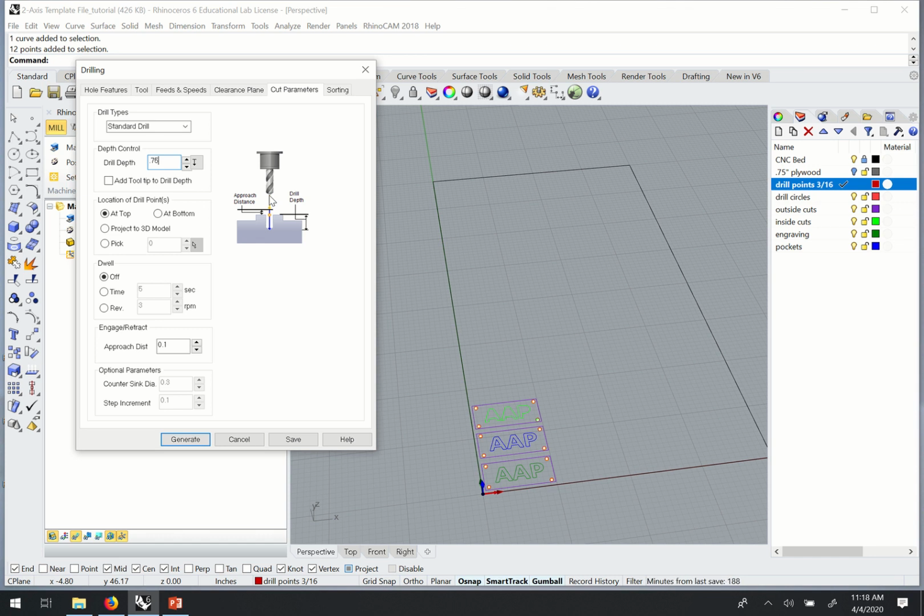And the CNC machines have what are called soft limits that prevent the machine from going too far negative. If it's programmed to go -1 inch, it will not allow you to do that. It'll sense an error and throw an error. And the threshold for that is -0.025 inches.